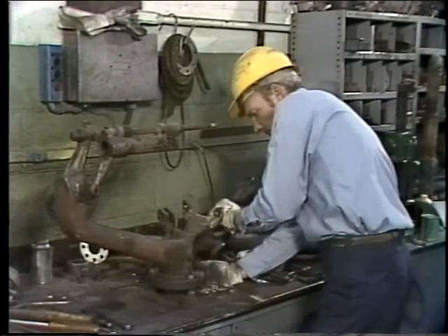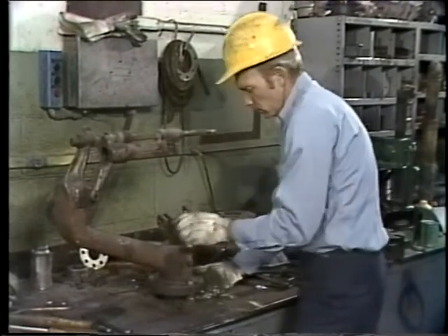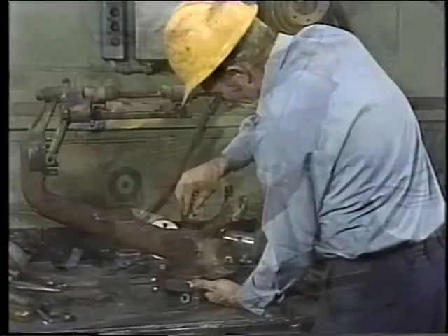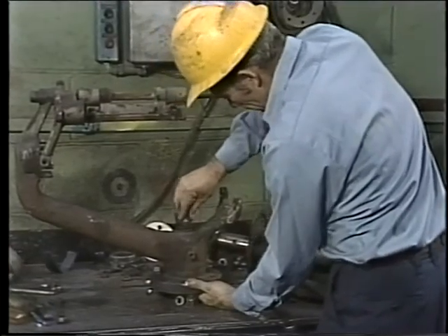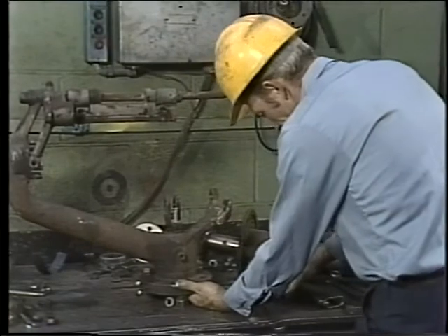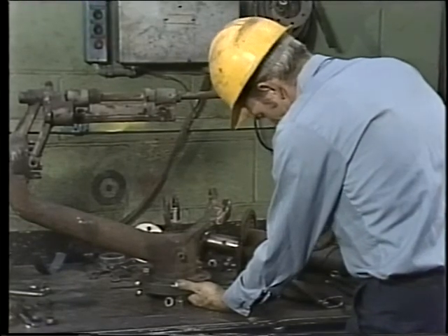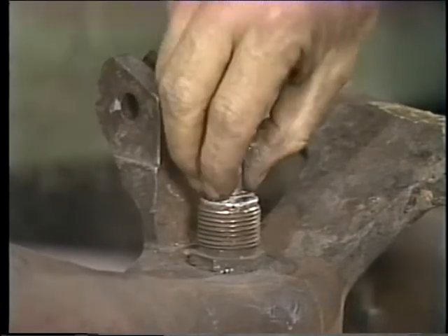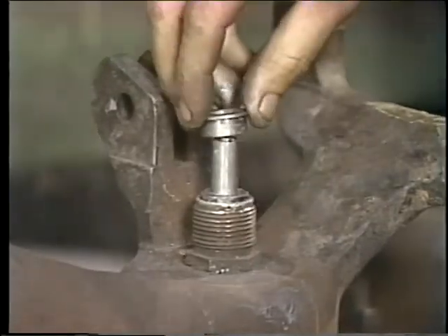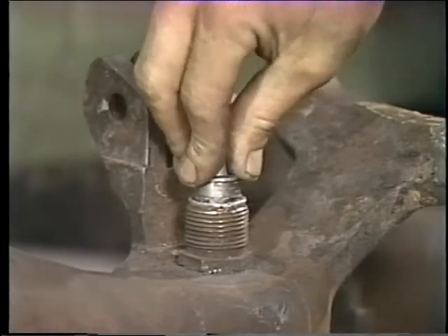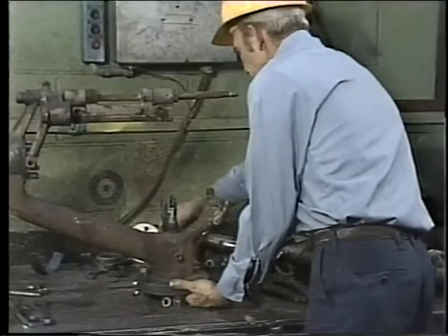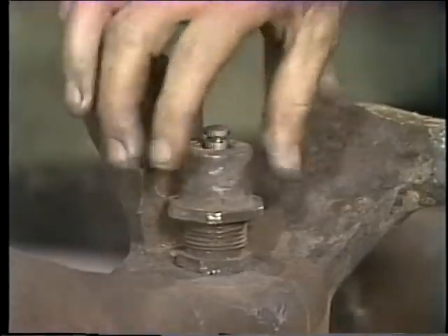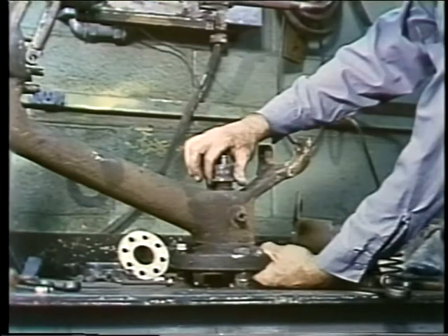With the disc in place, the soot blower is bolted to the bench fixture for ease of reassembly. Holding the disc up against the seat, he installs the new packing piece by piece. Just like any good packing job, the gaps in each ring are staggered. This keeps any leakage to an absolute minimum. As soon as the last ring of the packing is in place, the gland follower is installed, just finger tight. Final tightening of the valve packing will come later, when the trigger is in place. For now, finger tight is good enough.